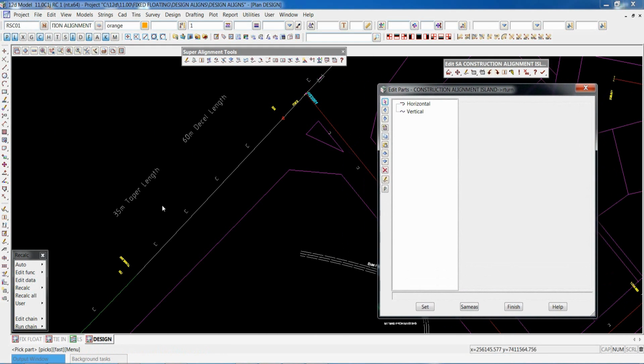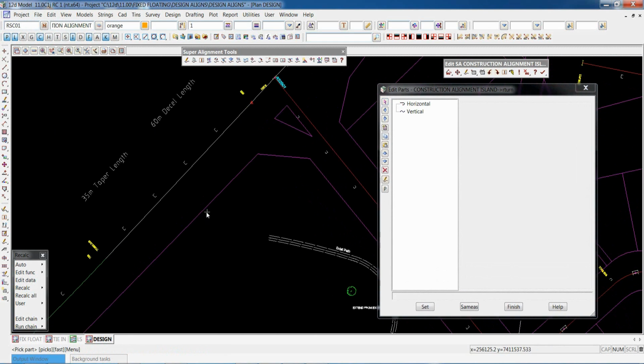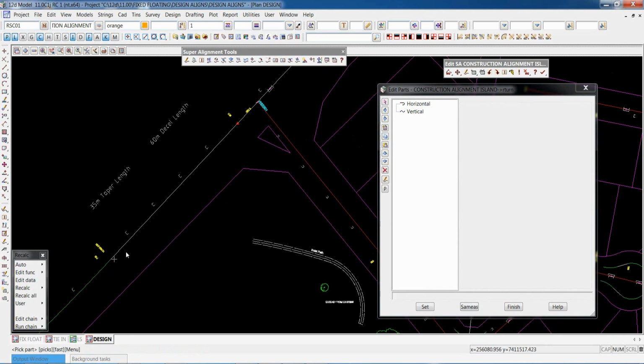So the right turn lane, we're going to look at a position here at the tangent point. We then want to be able to go a certain distance, put in a fairly reasonable taper with some 2 radii in it, and also then introduce offsets from the road centre line for the right turn lane. Fair few parts, but the taper option is combined all in one, like the fixed compound we've already seen.